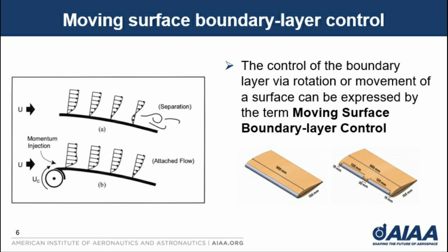It presents the study at low speeds and high Reynolds number using a symmetric and an asymmetric aerodynamic profile, which are NACA 0021 and NACA 23018, respectively, and comparing the results of these aerodynamic profiles with and without the rotating cylinder. With a moving surface, an attempt is made to delay the separation of the boundary layer from the wall by injecting an additional impulse into the boundary layer and preventing a growth of the boundary layer by decreasing relative movement between the surface and the free stream.